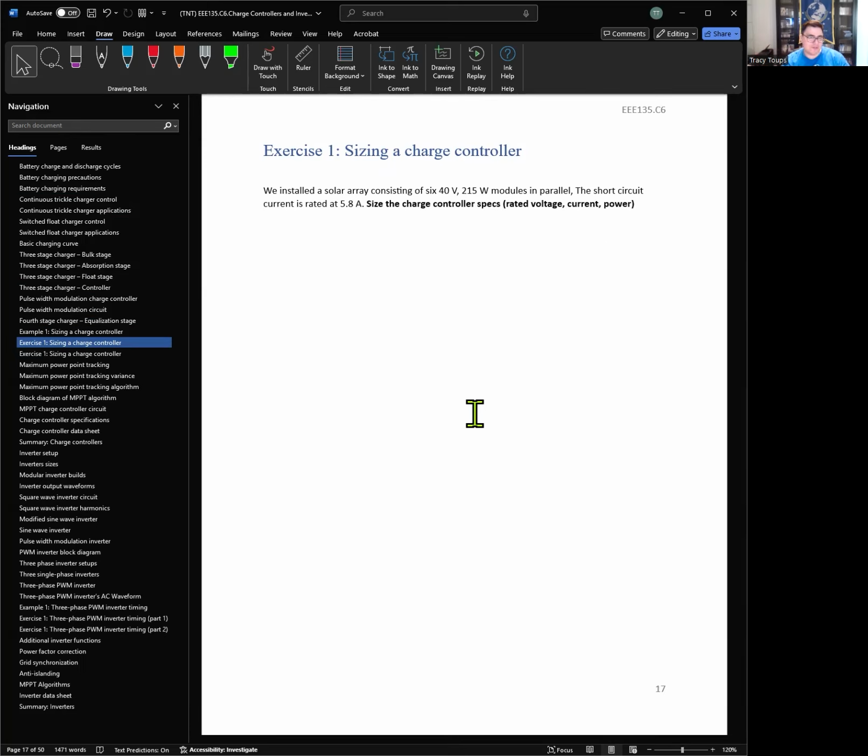And then you're like the middle person taking a solar array company and a charge controller company, and you're mashing it all together and knowing these small little nuances of this needs to match that with a 125% rating. That's what your job and that's what your expertise will come into, right?